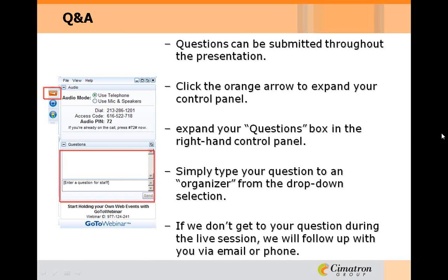Yeah, absolutely. Well, mirror, we showed a little bit of it, and you saw that when I mirrored the surface, it was a copy. Mirror is something that we're working on right now because it's at a basic level of functionality. What mirror will do is always copy. It doesn't move. So if you've got an existing tool design and you want an entire mirror of it, it's going to take you a little bit because it will certainly pick the parts, mirror them over, and you'll have that copy. If it's two parts in one mold, then it's really not any different than what I was showing. Instead of the one part twice, you'd add the left on one side and the right on the other and work on them in that fashion.